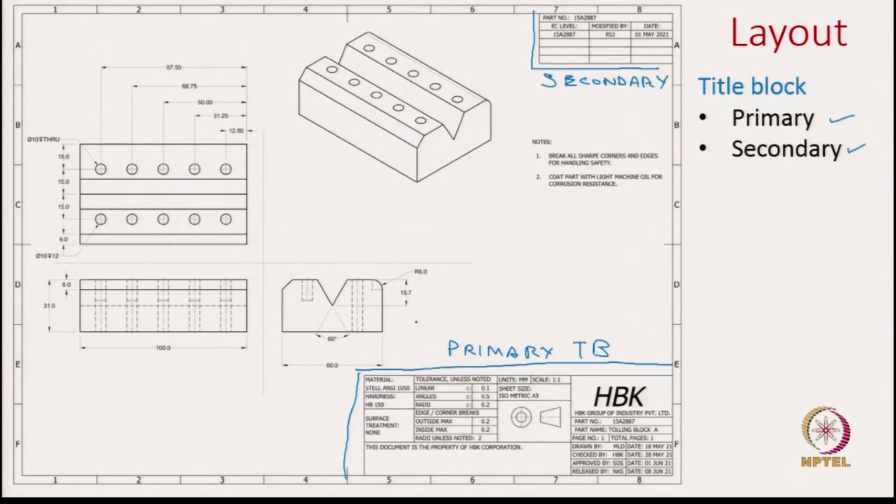So, let us see what else we have in this drawing. We also have a border. If you notice, there are these two parallel lines which go along all boundaries of this drawing sheet. What we see here are two aspects. One is called the grid reference. If you notice clearly, we have this grid reference in numbers 1, 2, 3 and so forth in the horizontal direction, and in the vertical direction we have alphabets A, B, C, D.